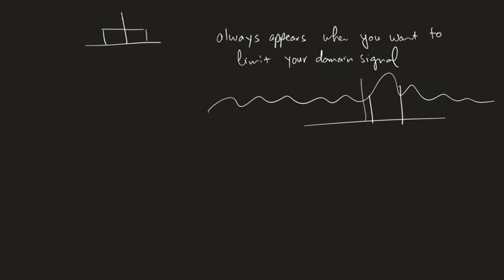And if you want to cut part of the signal, this is only done by multiplying with a square, right? With amplitude equal to 1. And the width, the start and the end of that square is where is your start time and where is your end time, right? So in time domain, typically, if you want to cut part of the signal, you multiply that signal by that square function.